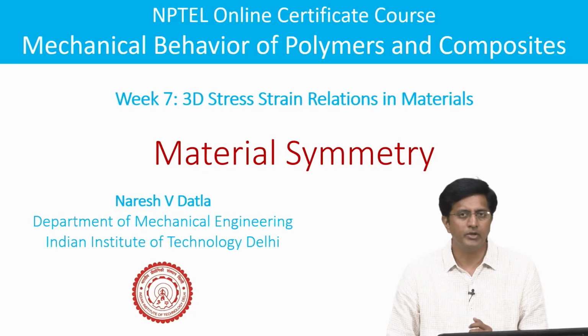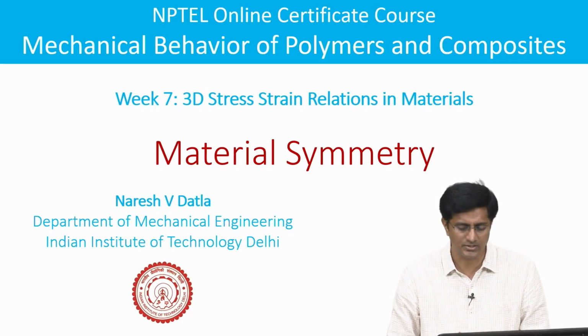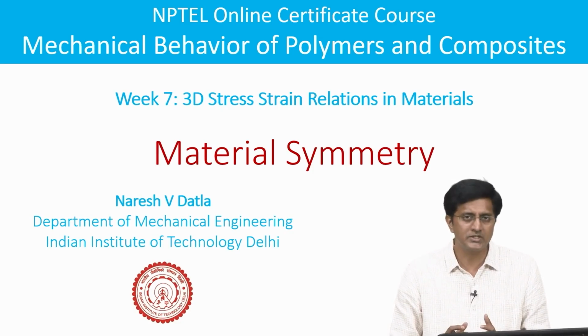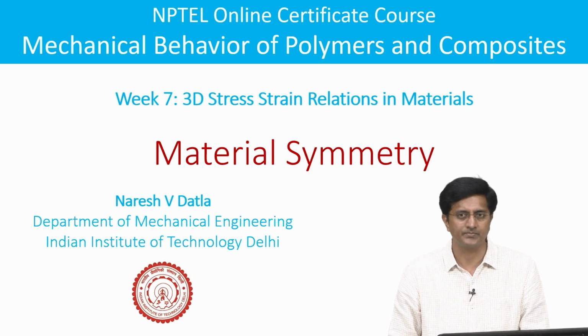Hello, in this video we will be looking at material symmetry and how it helps to reduce the elastic constants in the stress strain relations. Continuing from the previous video, we started with a generalized Hooke's law for anisotropic material where there are 81 independent constants. We got it down to 21 considering both stress and strain symmetry as well as the existence of a strain energy density function. But in this video we will see how we can further reduce it from 21 constants all the way to 2 constants considering all the material symmetries.